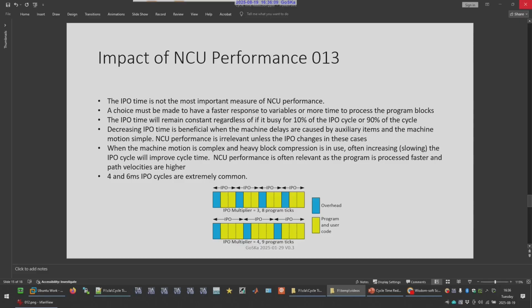If you run into the case where you're doing very, very simple motions and you're just trying to do things fast, maybe you can even take one more tick off of that. I don't know. But for example, if you have big flowy programs, like big 5-axis contours, and you're doing mold and die parts, the opposite can be true, because processing a large complex program in look-ahead is CPU intensive.